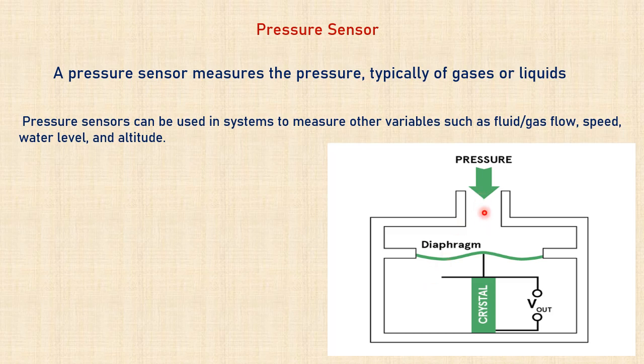So when I send the gas or a liquid here, due to the pressure difference on either sides of this diaphragm, the diaphragm starts to oscillate or vibrate. So when there is a deformation in the diaphragm, this mechanical deformation is carried to a piezoelectric crystal.